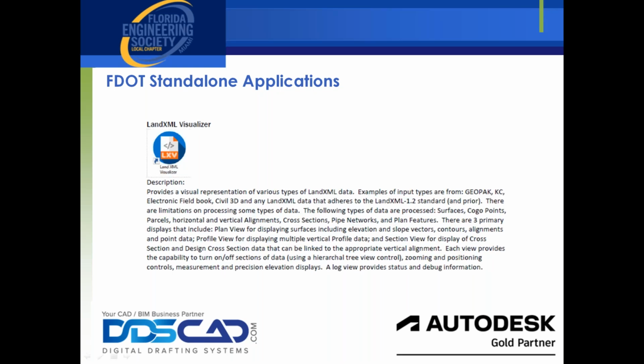All right, the Land XML visualization tool, or visualizer tool. This is a tool that allows us to look at Land XML files outside of Civil 3D. As long as they follow the Land XML 1.2 format, we can look at them. They can be surfaces and COGO points and horizontal and vertical alignments and cross sections, the pipe networks and plan features. We can look at them in the plan view, in a profile view, and in a design cross section, or a section view. We'll try to look at that if we have time.